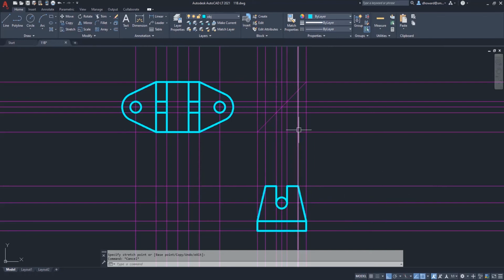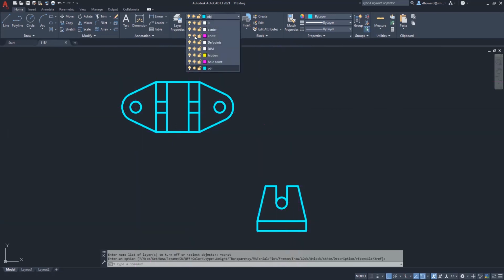Okay. And again, the way I knew that is it shows on the drawing that the distance from this line to this line is 1½. So I just offset the center line half of that distance on each side, which is 3/4 of an inch. I'm going to turn off my construction lines for a minute and trim out this piece here. The other thing I need to do while I'm here is put the radius on this corner. So it shows that as being a 1/4 of an inch radius.